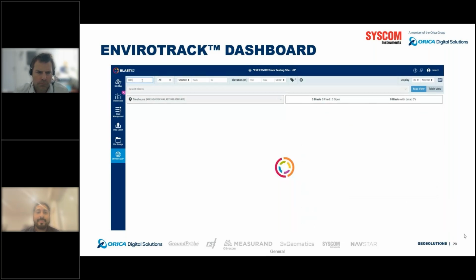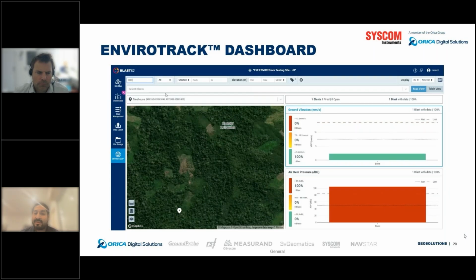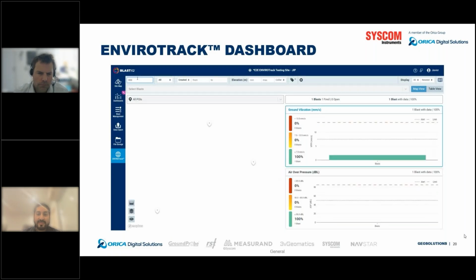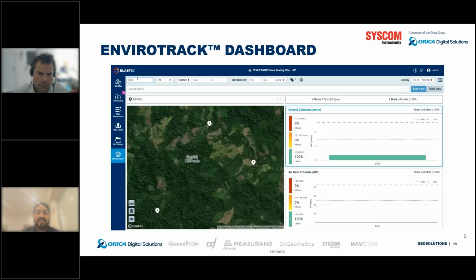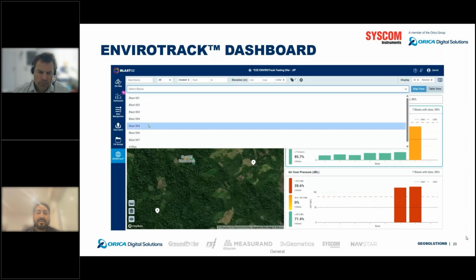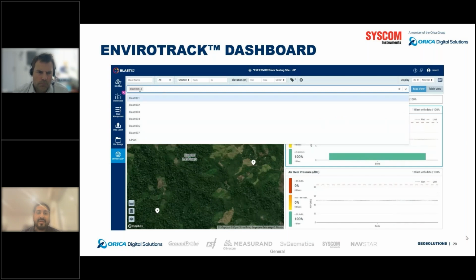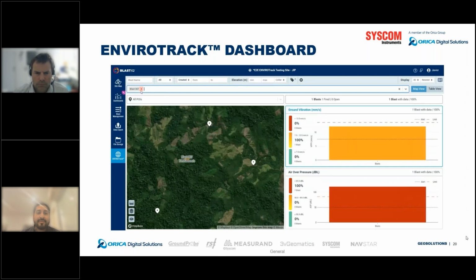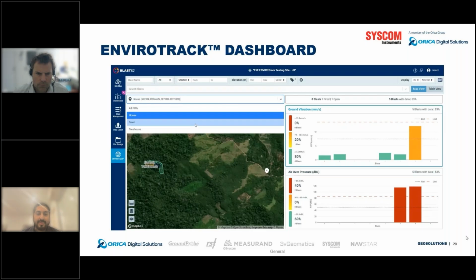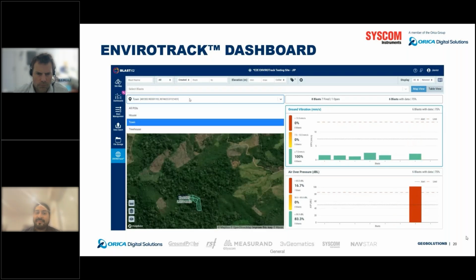For example, the blast 007 has the result you're being shown on the screen, and this can be selected for any point of interest or multiple points at the same time if needed. We can also use the blast selector to select a different blast, maintaining the POI as point of interest references. We can also use the blast selector to select one or more blasts for which we need reporting. As you can see, that lets the data be reported on the plot graphs.